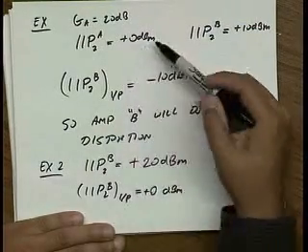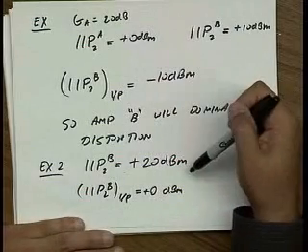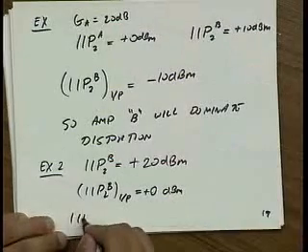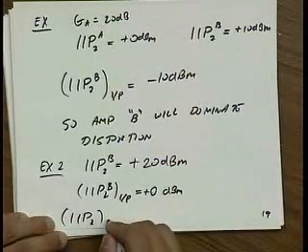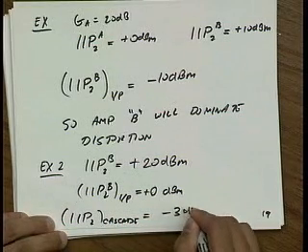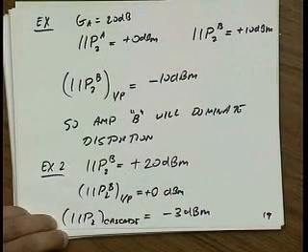And it's equal to the input IP2 of amplifier A. So basically, my cascade formula says I take these in parallel, and so the overall input IP2 of the cascade is minus 3 dBm. Okay?